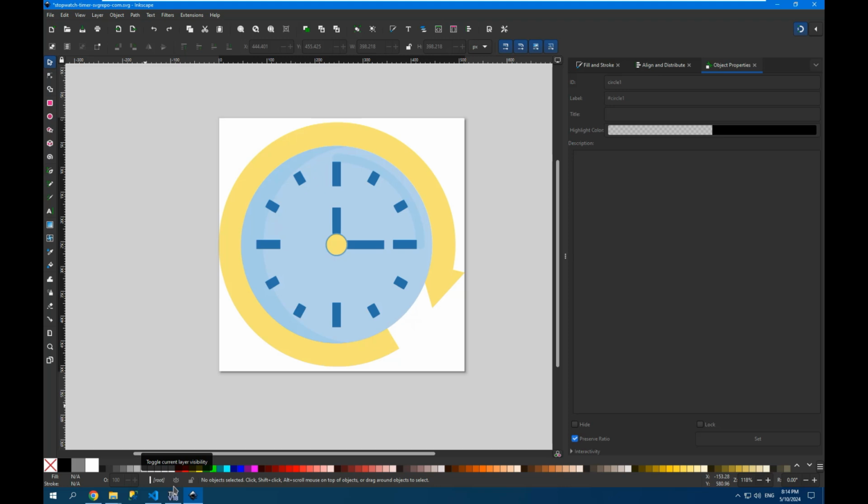Let's open the SVG image in the vector graphics editor. I'm using Inkscape and set the ID here. When we open the SVG image, you can see that there is already an ID here, but that doesn't mean that they actually are. Inkscape, when you open a picture, assigns an ID to each object. If there was an ID, Inkscape doesn't touch it. If there was no ID, Inkscape will make one up, but will not add it to the file.